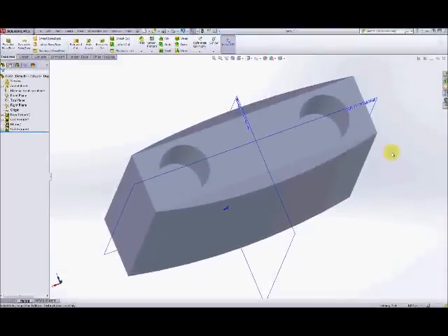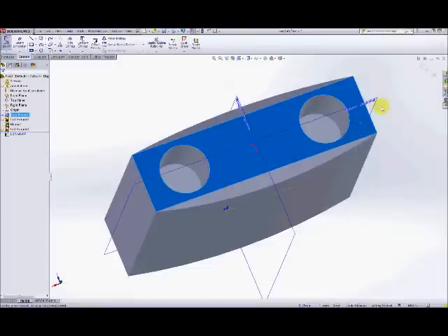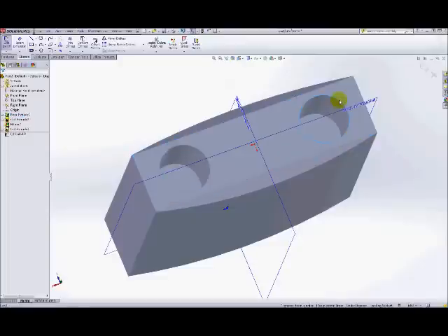The next step is to create the shackle for the padlock. Now the way I'm going to do that is I'm going to start by creating a sketch on this top face again. So go to create sketch. Now the shackle needs to be slightly smaller than the holes. Generally this sort of thing needs a bit of a clearance. So what I'm going to do is use the edge of this hole